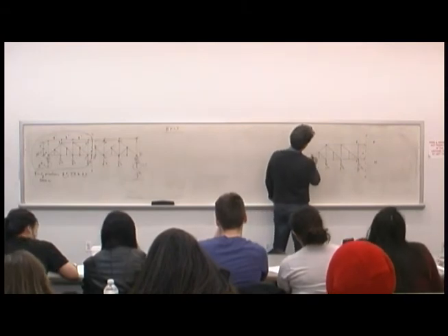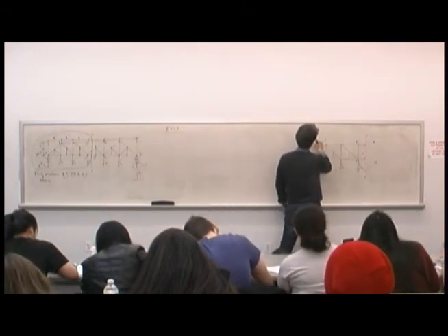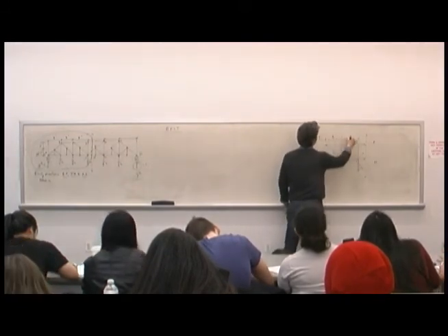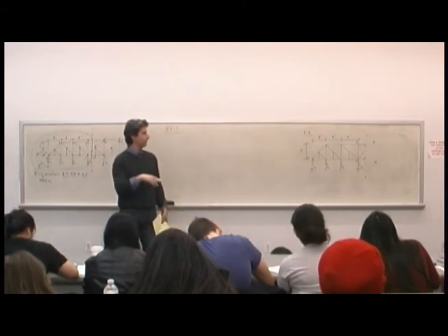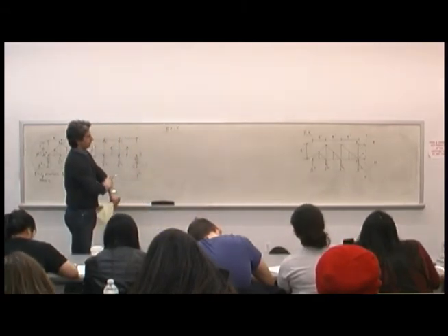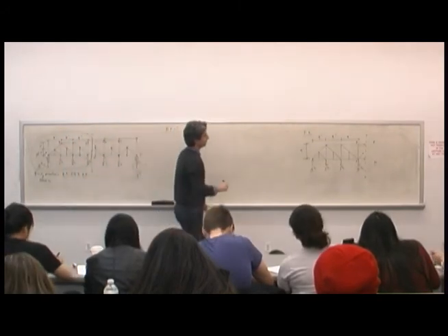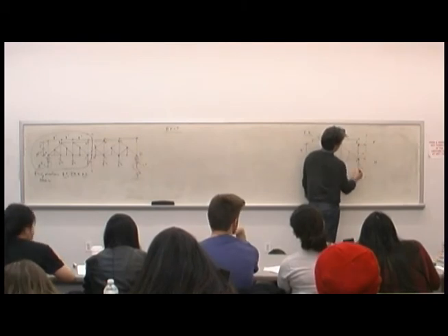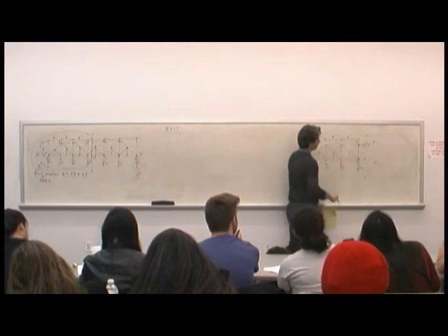This thing is 4 feet here, and we have 4-foot modules, all 4-foot modules and 4 feet high, so dimensions are not that difficult to figure out. But if I want EF, what do I want to do? This is my node. I'll cut these forces. Remember, I'm looking for that.